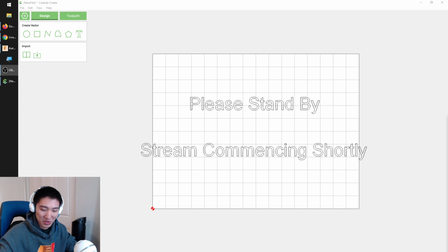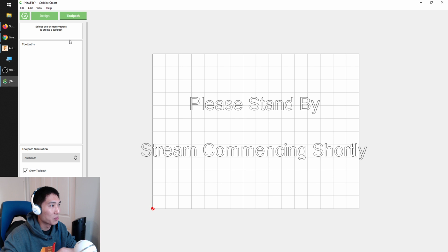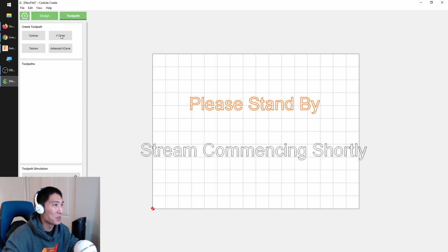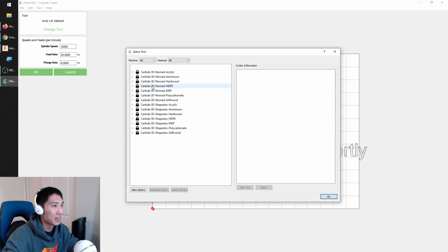Let's see, quarantine stuff is crazy, so I was thinking we might start out with just some really basic sort of what's new in Carbide Create. We just put out a video on Thursday about a new feature called Advanced V-Carving. And the way that works is, well, let me go over first how regular V-Carving works. You pick a contour in Carbide Create, you hit V-Carve, you pick a V-bit, and then